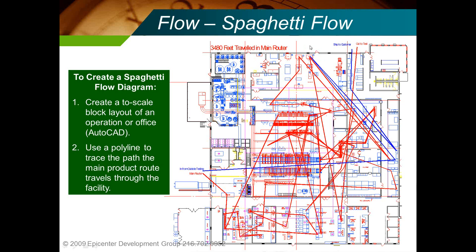they came up with the idea of duplicating that piece of equipment and locating that equipment in strategic places. These are all clean room type environments, and everything is moved by cart. So it was a significant reduction in the time for them to get the product through. They had like a 3-week turnaround time, and we were able to cut a week of time out by just looking at this material flow, spaghetti flow diagram, and making some changes to the amount of equipment and where equipment is located.